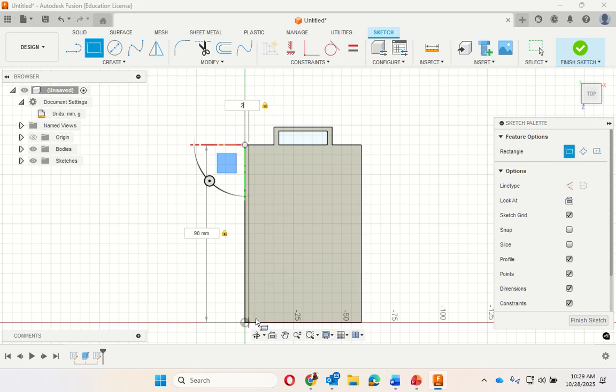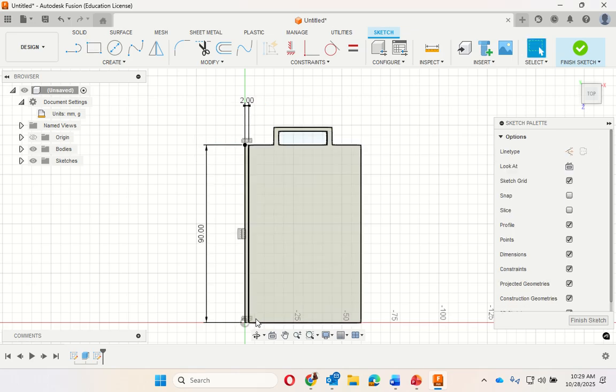When you do this in plastic and you're making a picture frame, pictures are very thin. You don't need a lot of space there. Like I said, I made this to fit an ID. The ID is only so thick. So 2 millimeters is wide enough to fit in and out of there. Hit enter. And I need to do that again here and on the bottom.